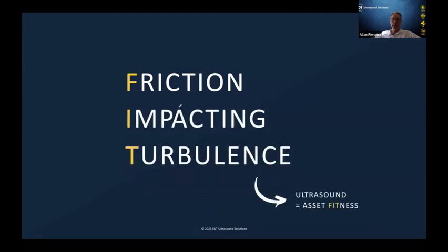So understanding a little bit about sound and the heterodyne and where ultrasound fits in the P to F interval, the next question you want to ask is, well, where the heck can I use it? Well, we want our assets to be fit. That's our job as reliability technicians, to create fit assets. When our assets are not fit, they give us symptoms of failure. And those symptoms of failure manifest themselves as friction, as impacting, or as turbulent flow. And so the first letter of each of those words forms a convenient acronym that we call FIT.